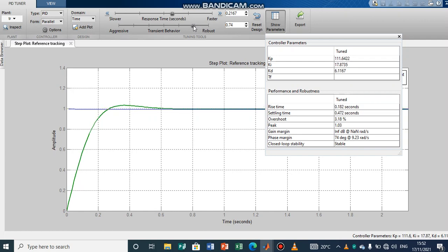Let me take this as our system, which may have a rising time of 0.1 and settling time of 0.4, and my overshoot has been reduced. Before, I had like 80%. So I'm going to copy these values and run them in our MATLAB, to see our new graph.